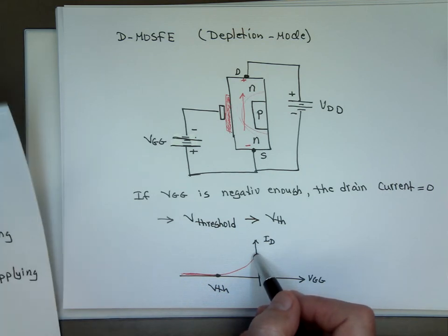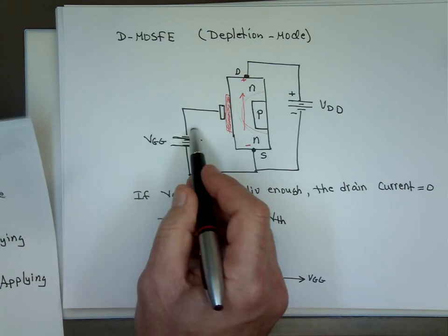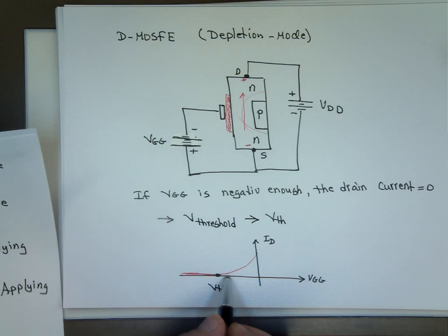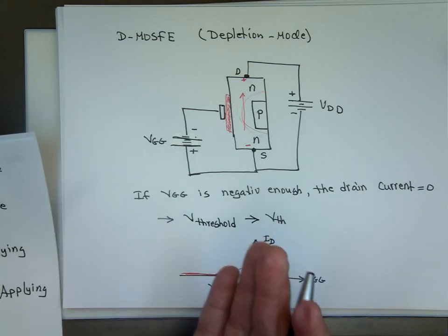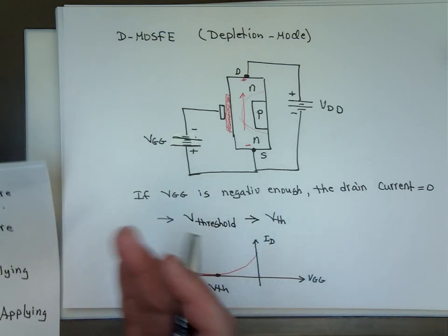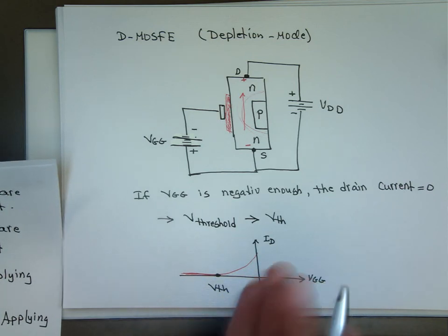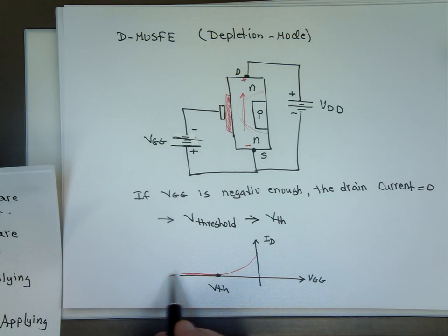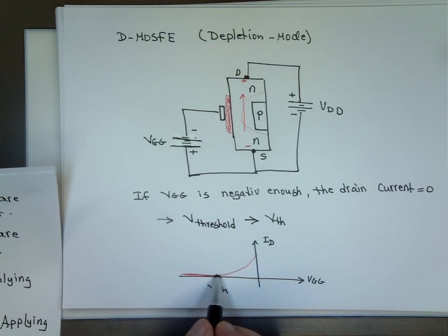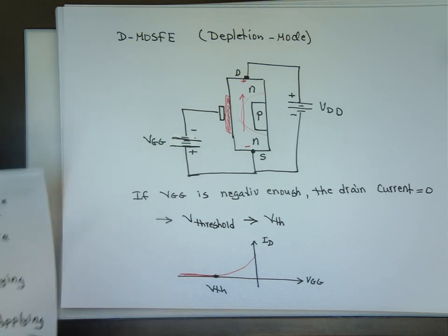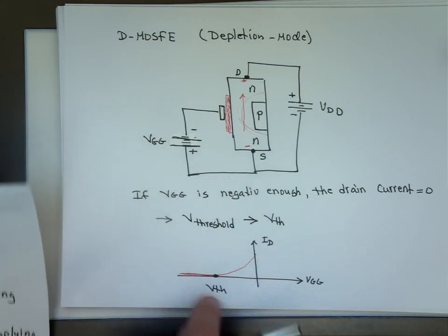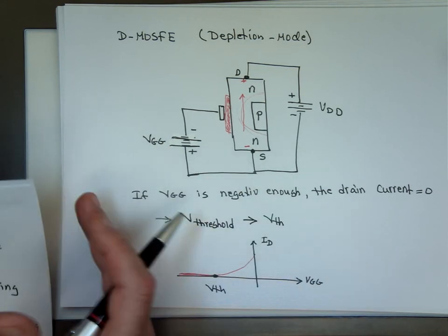But as you start applying that voltage, negative on the top, plus on the bottom, and increase the absolute value of it, because -4 is not mathematically bigger than -3, but the absolute value is. As the values get larger in this direction, that current starts to decrease till it hits zero. And there's nothing going through, cutoff voltage. So when this value is below this number, that means you're in cutoff region or mode.